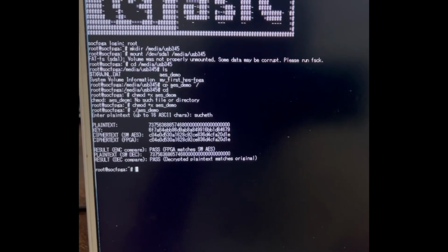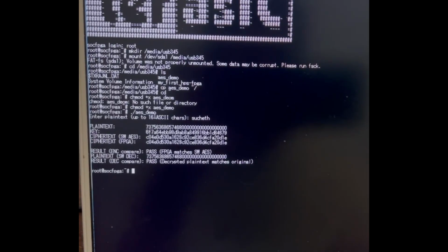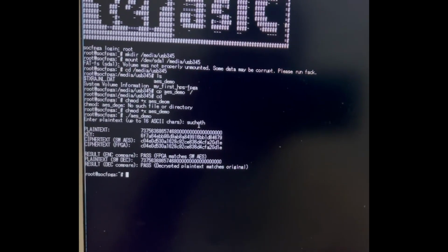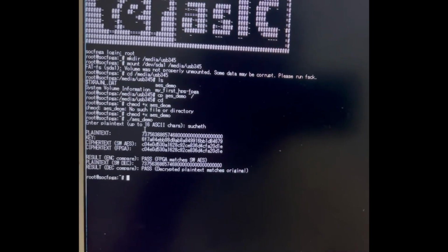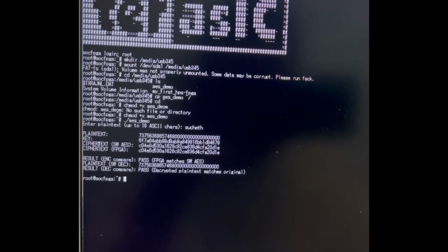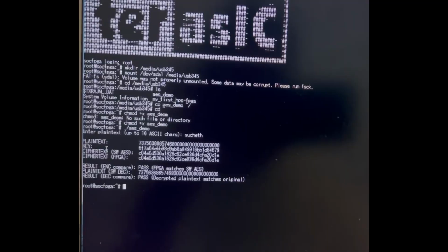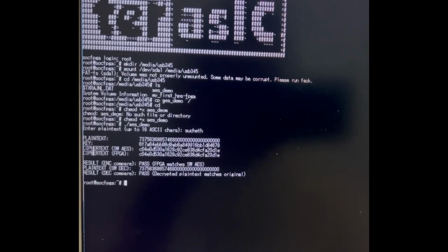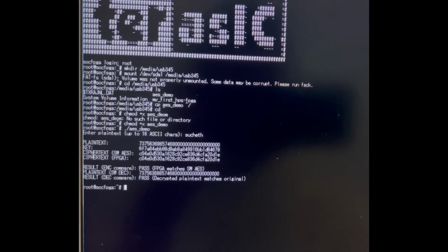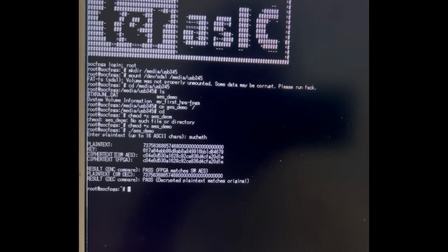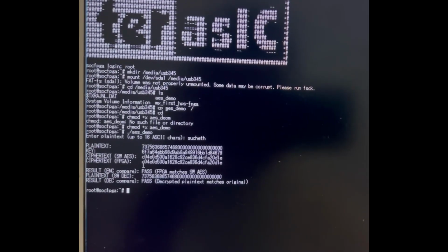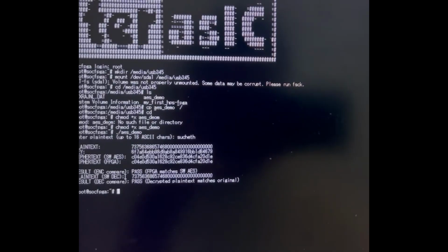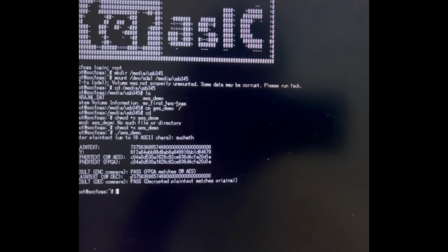As you can see, after giving the ./AES demo command, it's asking for a plaintext from the user, for which I've given my name, Suchit. Then it converts the plaintext from ASCII to numeric, and then it generates a 128-bit random key, which then goes to the FPGA board, and the FPGA board gives a ciphertext using the key. The software side HPS also gives a ciphertext, and you can see both these ciphertexts match and the result is given as pass. And you can see the plaintext decryption from the HPS software side as well.